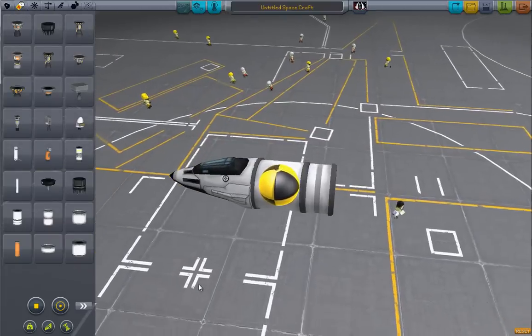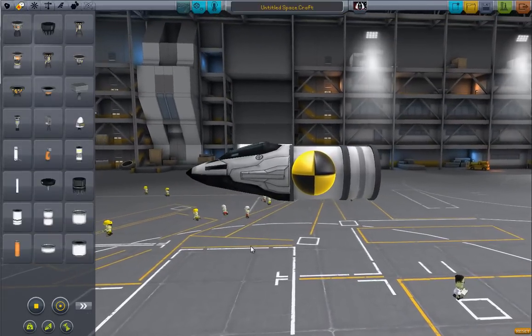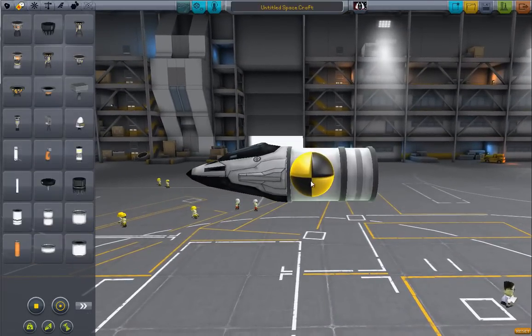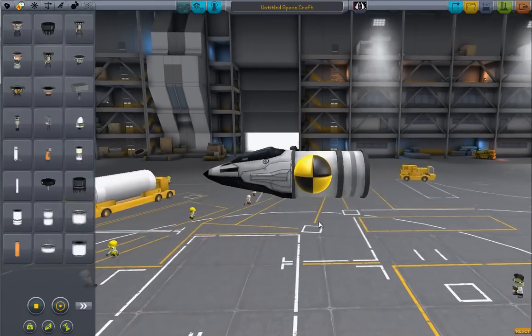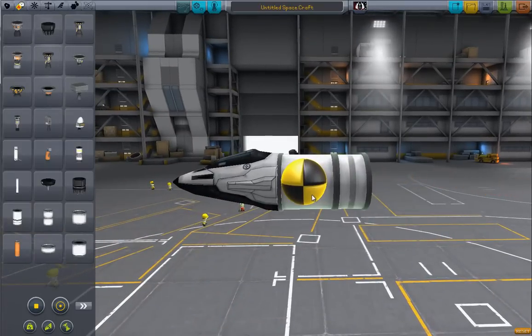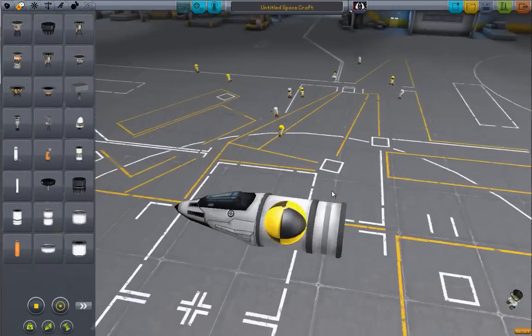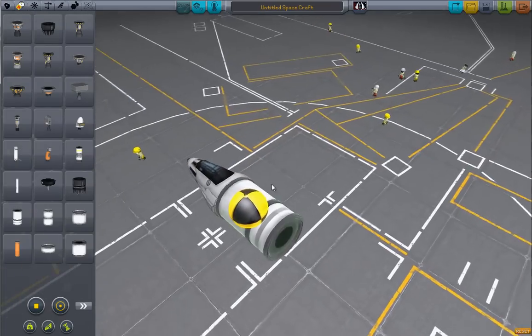When you're building a VTOL craft, make sure that your upward thrust is center, or at least close to the center, preferably just a teeny bit behind, because when you start running out of fuel, this will move. But yeah, your thrust close to the center of mass. That's basically it. Just make sure your thrust is close to the center of mass.